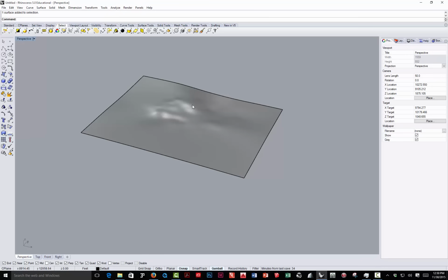So it's much more efficient to put the elements that you need in, like steps and walls, and adjust the surface of this terrain to fit those. And then once you've done that, you can split it into the pieces and apply the materials. The other thing that's really helpful in doing that, since the walls and the stairs are defined, but where those paved surfaces, the water feature and the seating area are, I can do that with an image map just like we did in SketchUp.